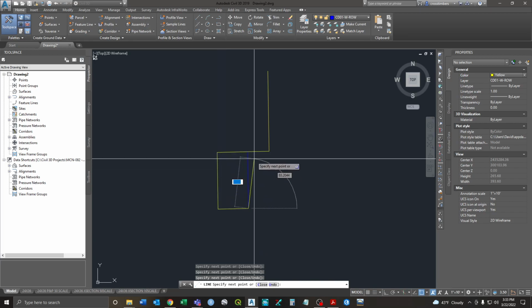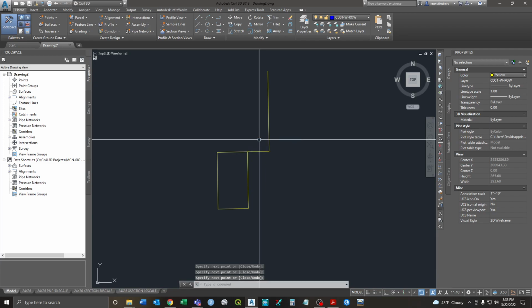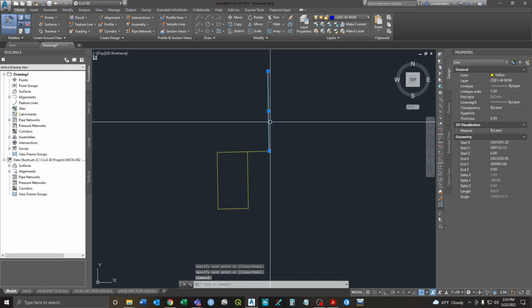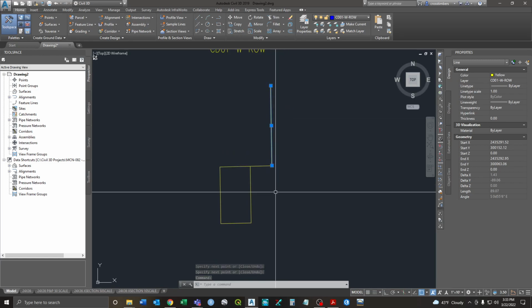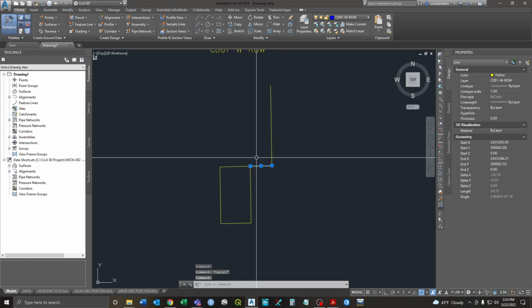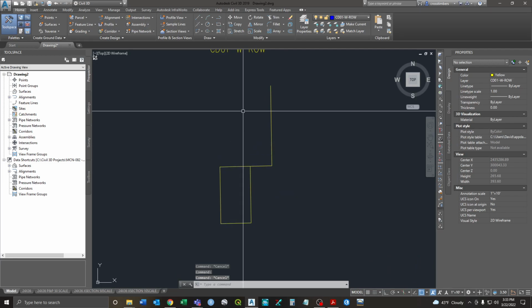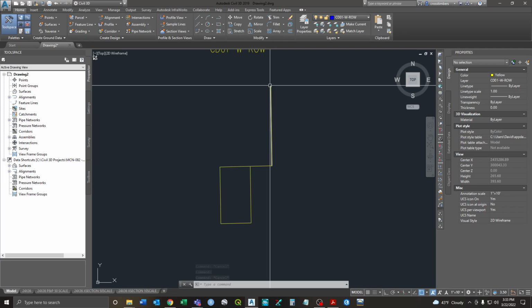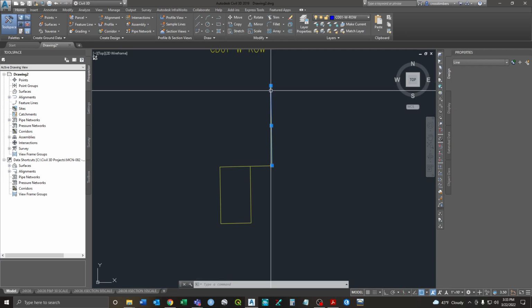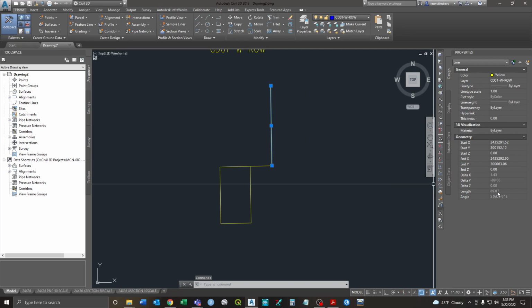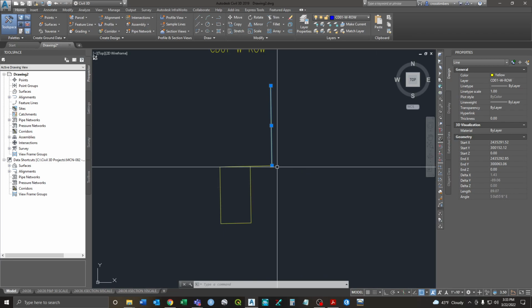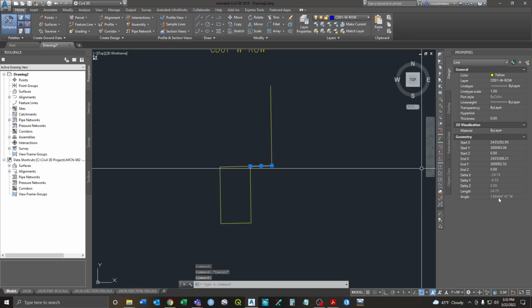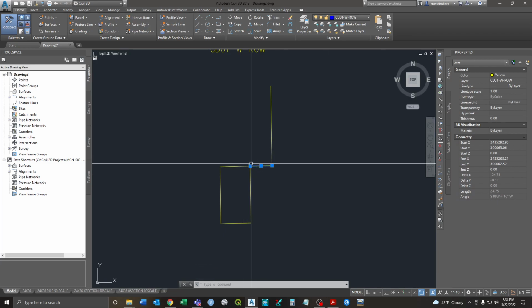And then just go around the corner, click here, now right click and enter. So now each one of these, we've got it all in individual chunks. If you think about it, you do it in order. So now we're going to start at this section corner, and then you click here, we're going to travel 89.07 feet at a bearing of south 0 degrees 55 minutes 6 seconds east here, then 24.75 feet at this bearing to the point of beginning.